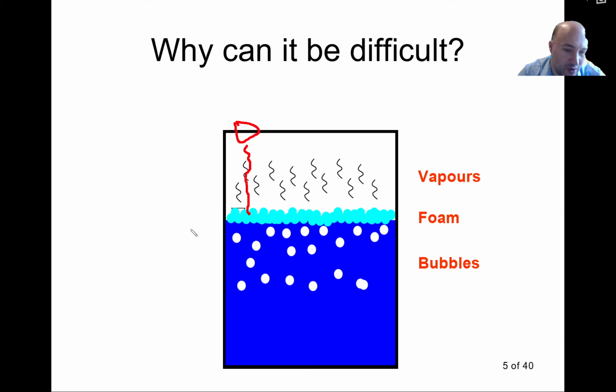It might also be an aggressive liquid or aggressive vapors, so we may have to protect the sensor from this chemical damage. For example, if it's a radar, it needs to have an antenna that is made from stainless steel.